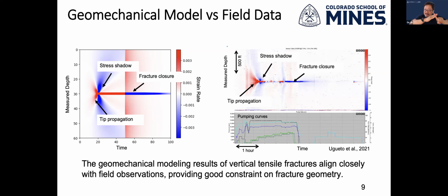For example, in this particular stage, we easily identify there are 3 hydraulic fractures, characterized by the extensional signal during the fracking and the blue compression signal after the pumping stops. So there are 3 hydraulic fractures that intersect my monitor well at these 3 precise locations. And also keep in mind that we're fracking the treatment well stage by stage.